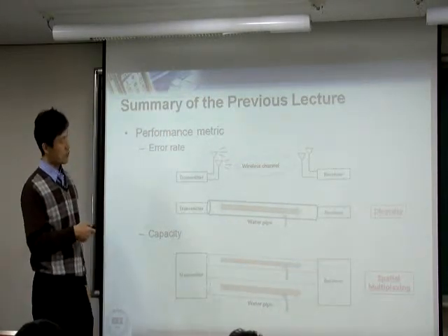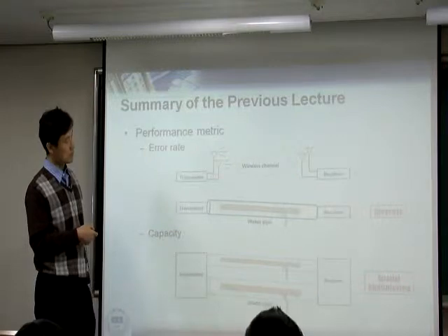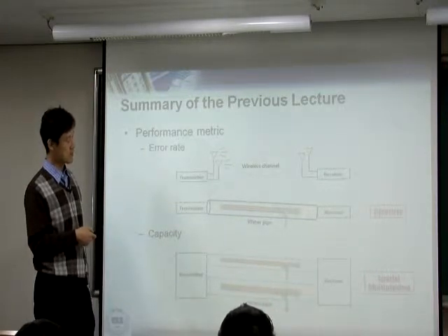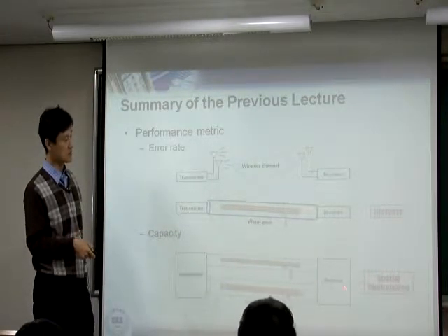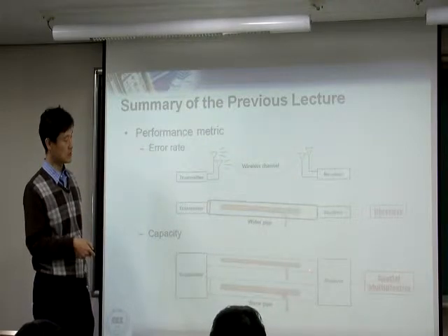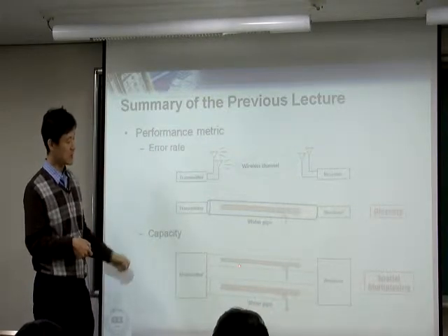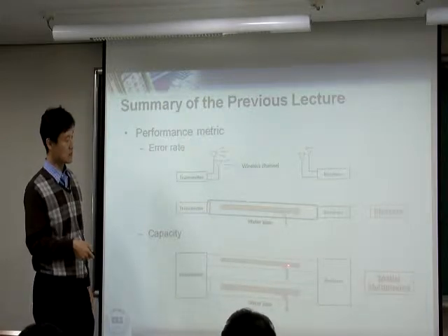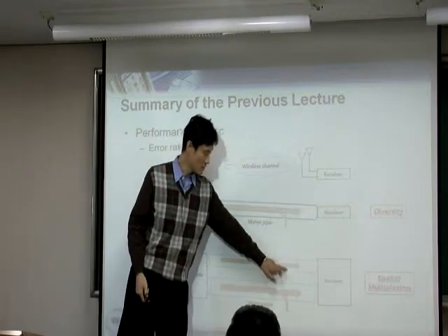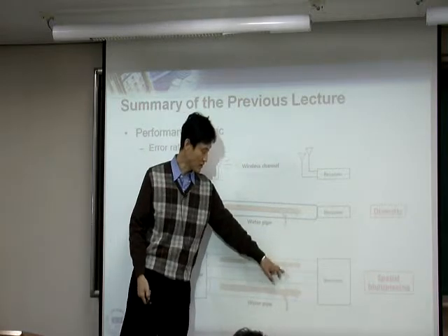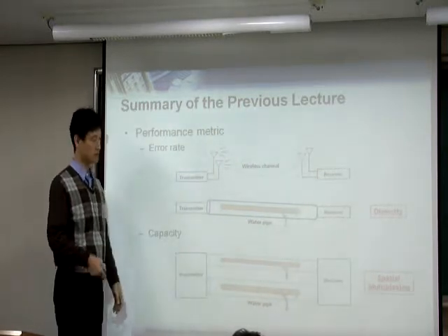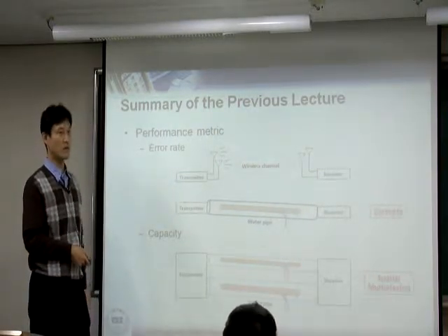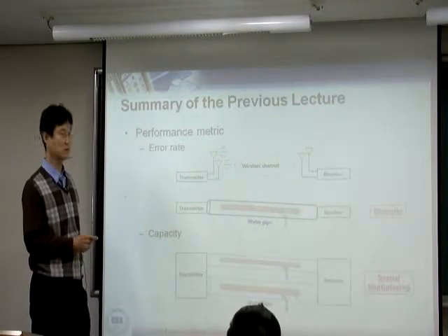Whereas when you use this 2x2 MIMO system, you can also run it as spatial multiplexing. In that case, you have two independent pipes, each one a normal diversity order 1. So compared to this one, it has a pretty large amount of errors, but we have two independent streams. Therefore, you can increase the capacity.